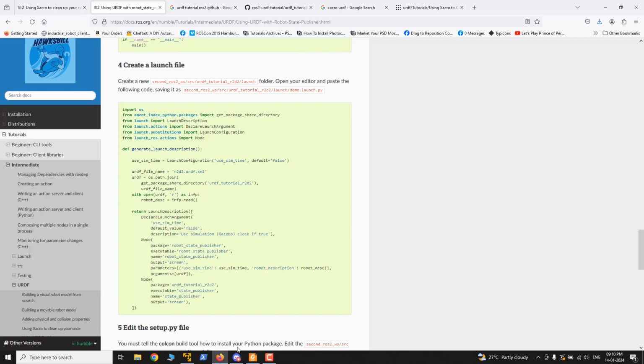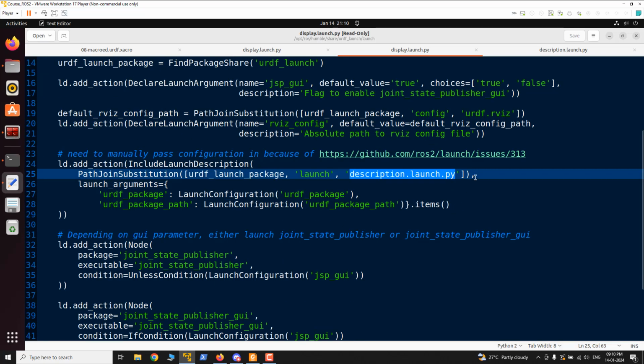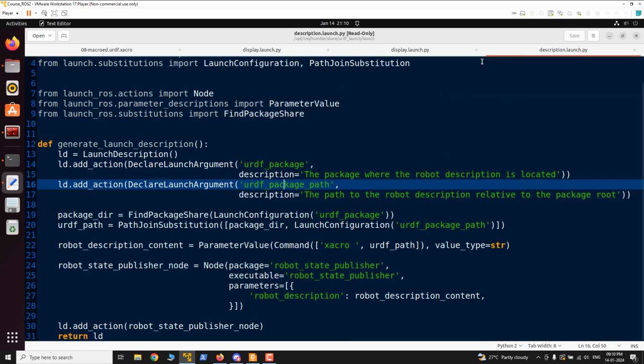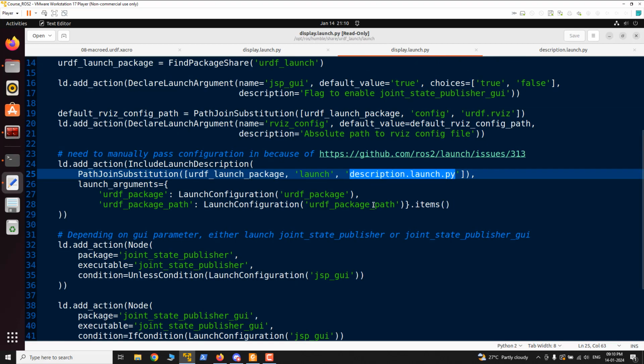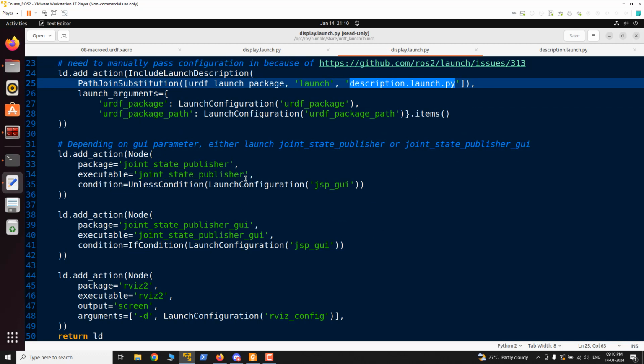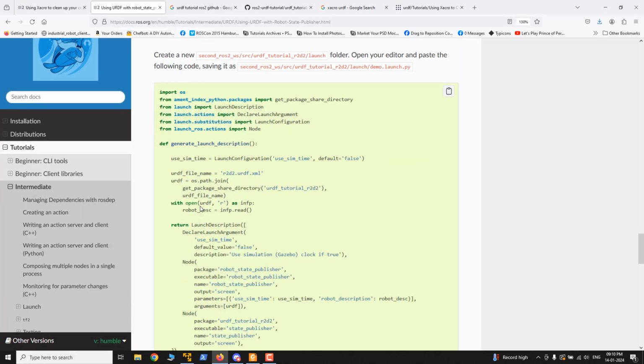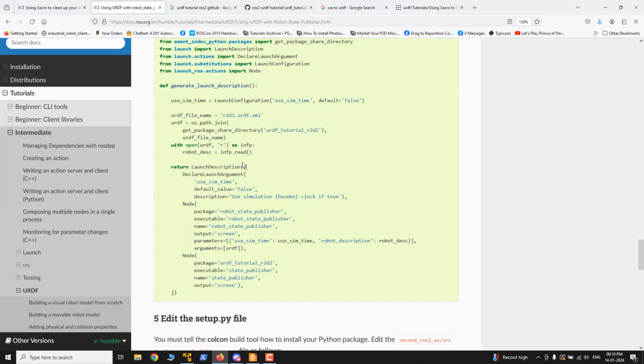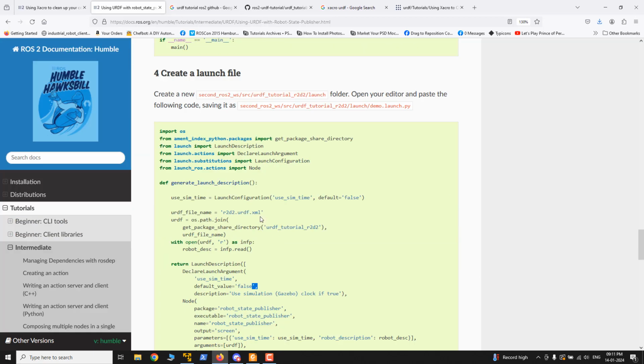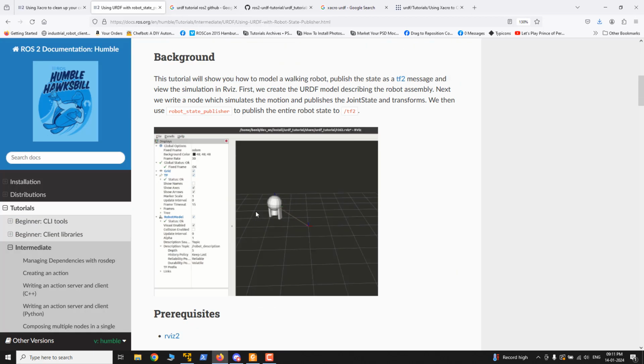Okay, so you will have a question why we need this much of launch file. It's basically for modularity. If you want some kind of modularity, in this launch file, if you check, it's very simple, and it only has the parsing of the URDF. And in this launch file, it is using the description.launch and only the joint state. So all these things, maybe we can also define in a single file. Maybe we can describe that in the next class. You can simply see the same thing that we have mentioned in the single one. We are parsing the URDF and then starting robot state publisher, all these things. Okay, so next class maybe we can continue and we can start with the simulation.